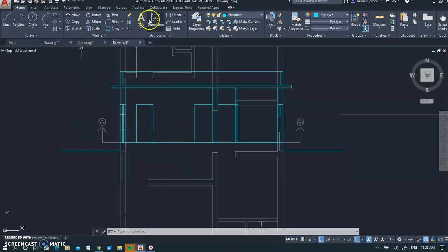So vertical measurements you can write by going to linear and just doing that. And if you wanted a suffix, as I told you earlier, go to dim style, and in there under suffix you can add m for meters, and you can also change the precision without any zeros. I'm not going to explain all that here. So linear measurements can be given by